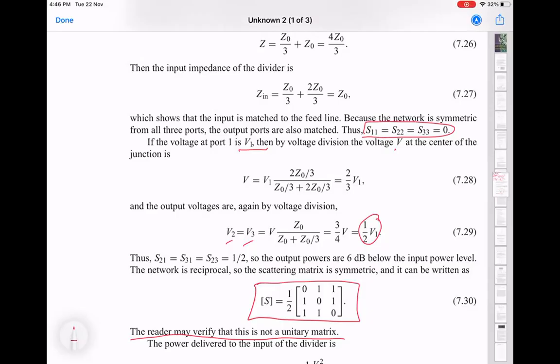This will work like a power divider all the way down to DC. That's why, if you remember, that box said DC as well. But at higher frequencies, there'll be a cutoff because you cannot make resistors work to arbitrarily large frequencies. So that again depends on the construction, how small it is, what kind of stray capacitances and inductance it has. One needs to worry about that.